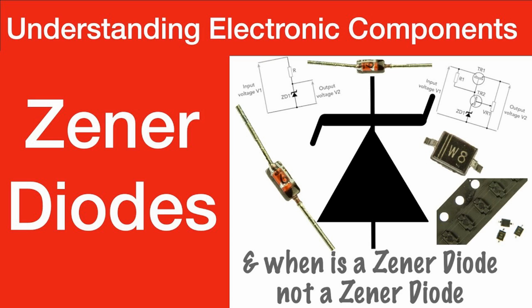5. Temperature-compensated Zener diodes. Description. These Zener diodes have built-in temperature compensation to minimize the effects of temperature variations on the Zener voltage. Characteristics. Designed with specific temperature coefficients to counteract the natural temperature dependence of the Zener voltage. Provide a more stable reference voltage over a wide temperature range. Applications. Precision voltage references in environments with significant temperature variations, such as outdoor equipment and aerospace applications.